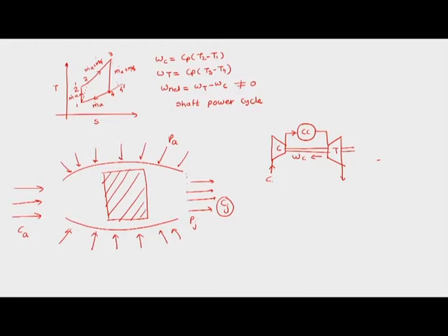So, we have Ca here and we have Cj here. Now it is going with higher kinetic energy as compared with the inlet kinetic energy. So, this change in kinetic energy or change in momentum would lead to thrust for the power plant or the aircraft. So, we are interested in generating thrust in case of power plants used for transportation applications.